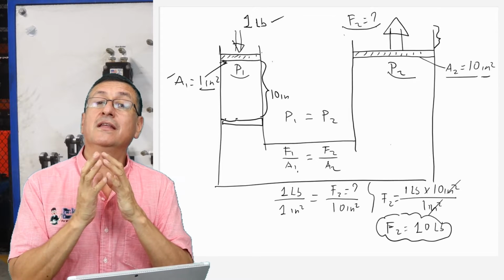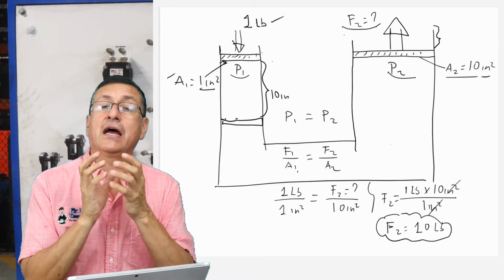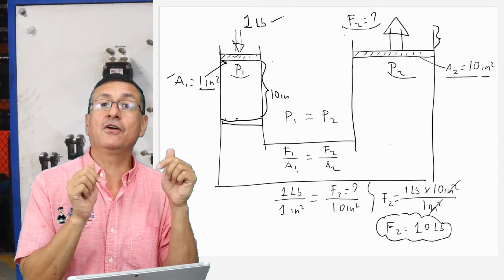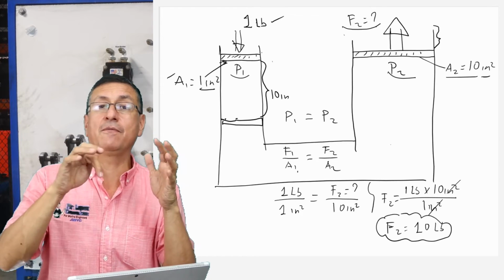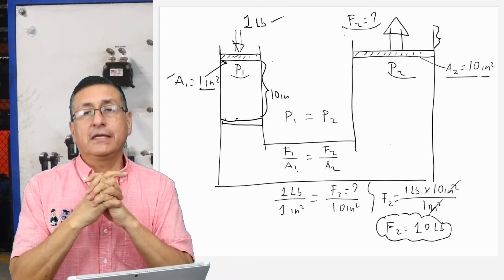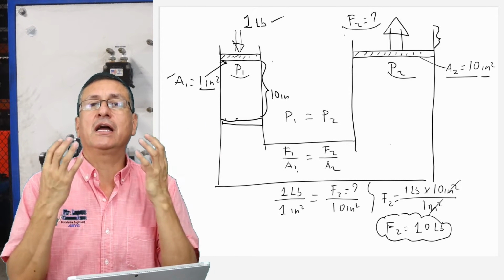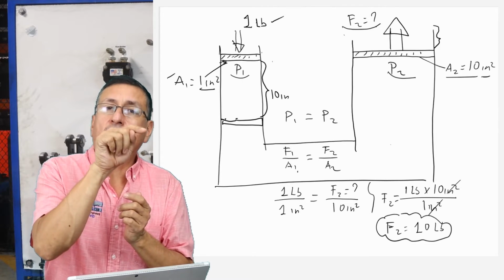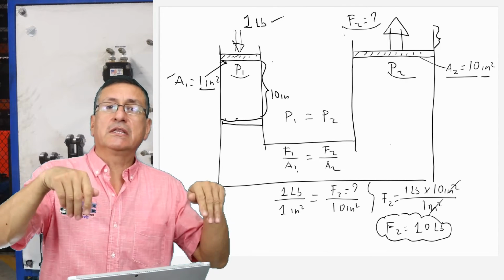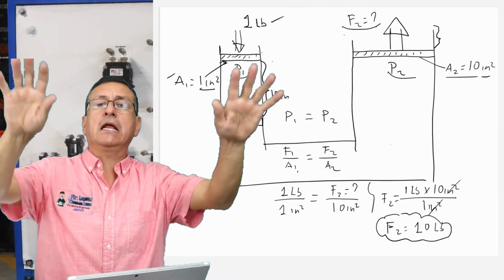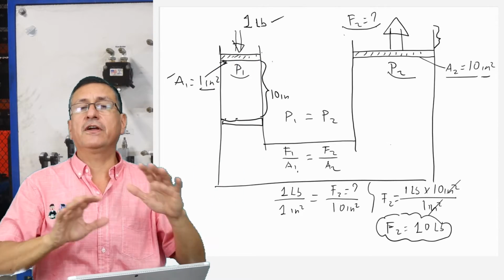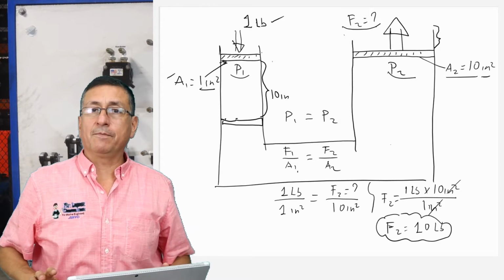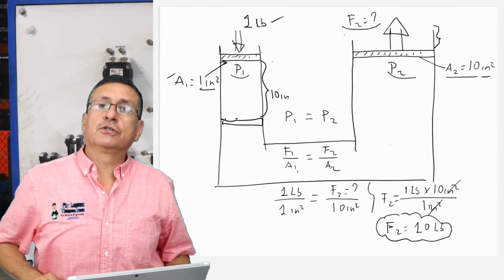We are going to study the different types of cylinders, single rod, double rod, single shaft, double, the different options. And in each particular hydraulic system in your boat, we are going to analyze the actuator for that system: the twin taps, the passerelle. For different situations, the actuators, the cylinders, are completely different. Alright, this is the output force.